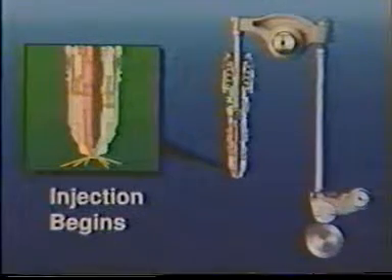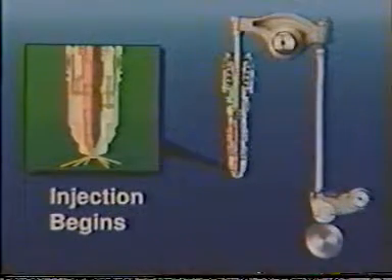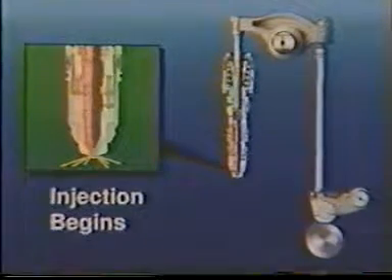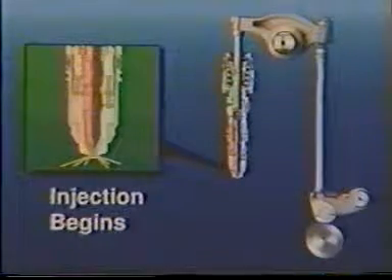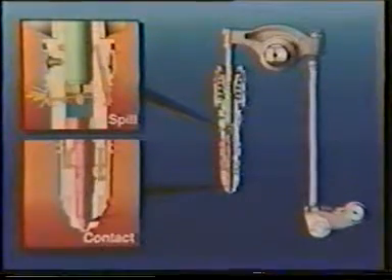The downward velocity of the plungers will increase as the follower continues up the injection ramp of the camshaft. When the pressure in the cup exceeds the pressure in the cylinder, injection begins. Injection ends as the lower plunger makes contact with the nozzle seat. At approximately the same time, the groove in the timing plunger aligns with the groove in the barrel, opening the spill port. The timing fuel then spills as the upper plunger continues its stroke.